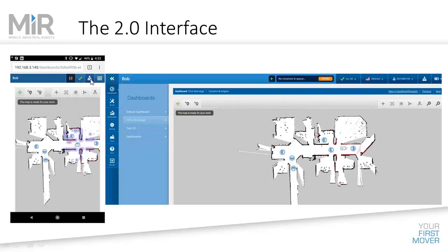That joystick is where you can take manual control of the unit. Say it's gotten itself totally stuck. People have boxed it in from both sides with fork trucks. After X number of retries, it'll send a text or an email at your discretion out to somebody to help it be rescued. A person may come over here, make a wireless connection to it, and use a joystick to drive it out.